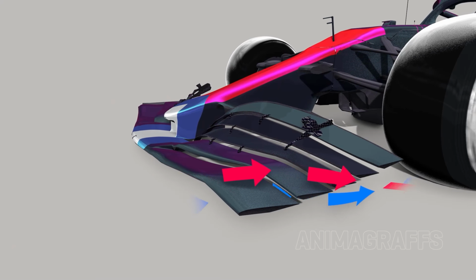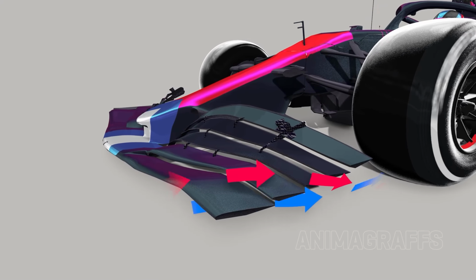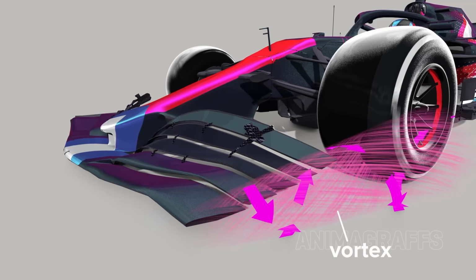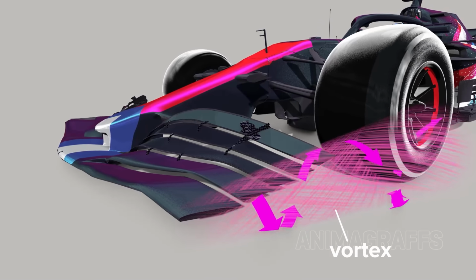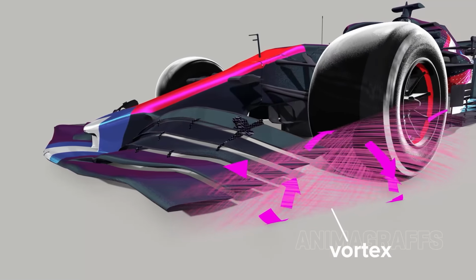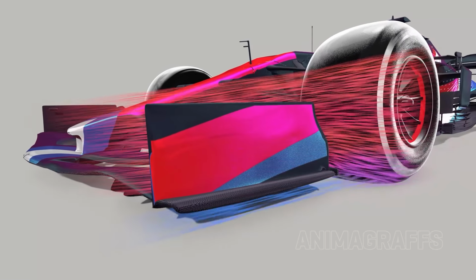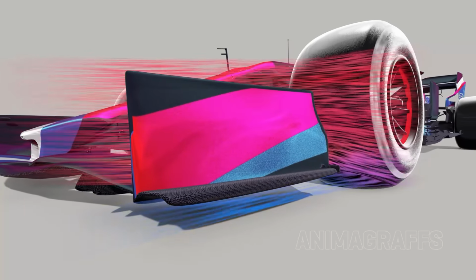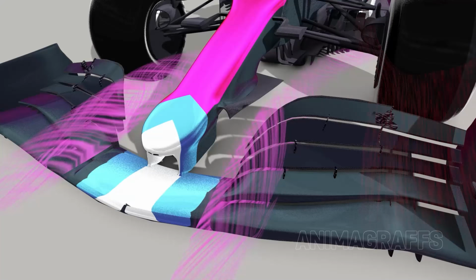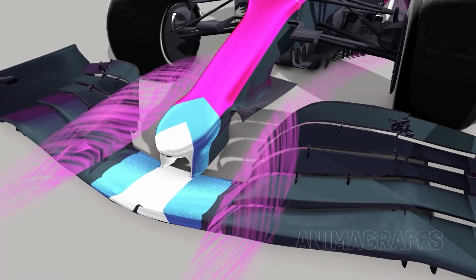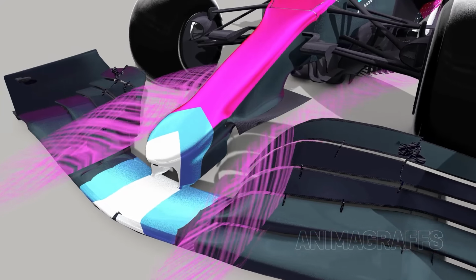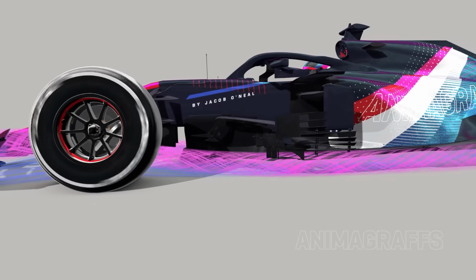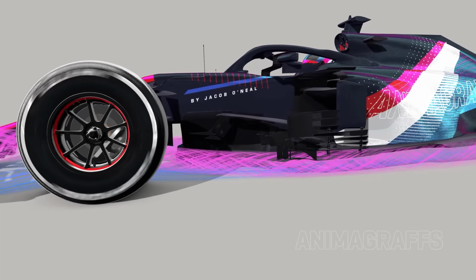Where the wing ends and these different pressure zones meet, the air crashes into itself, creating a spiraling vortex. Vortices cause drag, which tugs at the car, slowing it down. A cap on the wingtip interrupts vortex formation for a less intense effect. In contrast, the pointed, curved-in surfaces on the inside edge of the wing intentionally shape and direct a vortex around the floor of the car, sealing in the clean air that passes beneath.